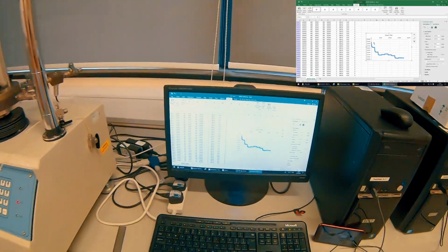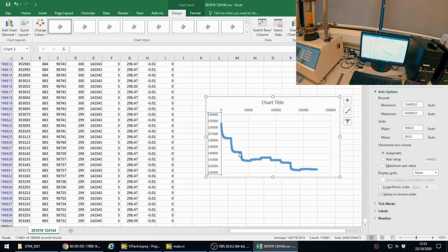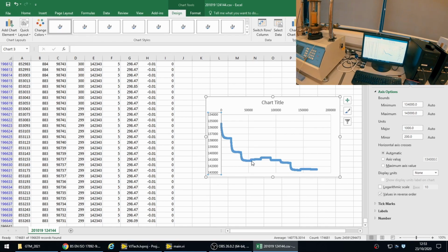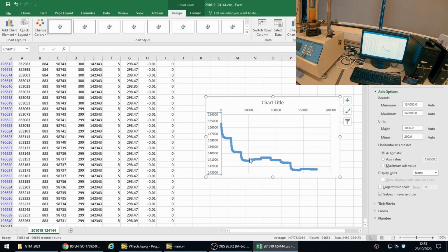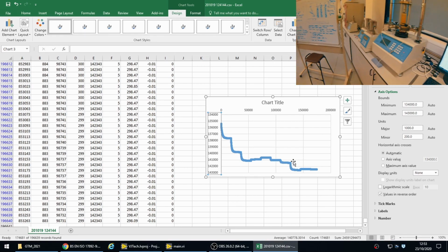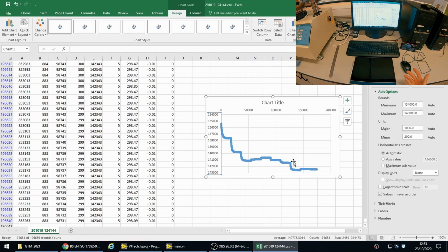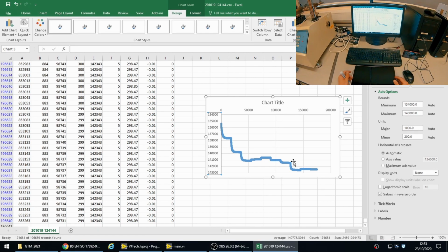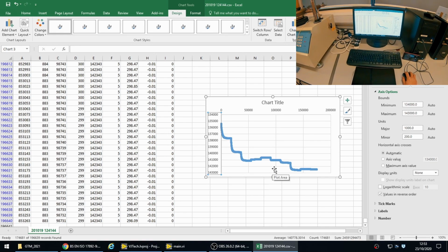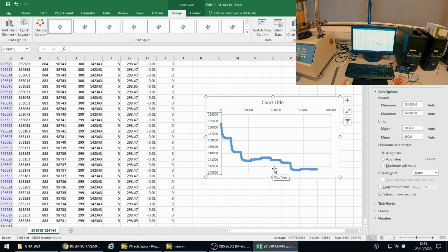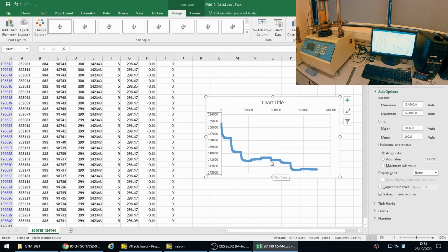And here you can see that where we are losing volume in our sample down the lambda line, the volume changes in the kappa line, where there is some swelling and recompression, are a lot smaller than they are in the lambda line. So that's good. It shows that we have an emergence of the type of behavior we'd expect to see from what we know of Cam clay. So that's good.